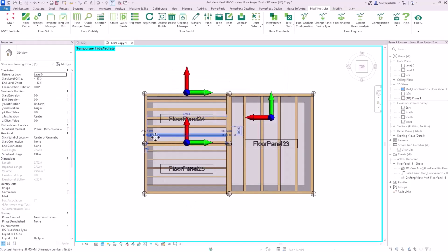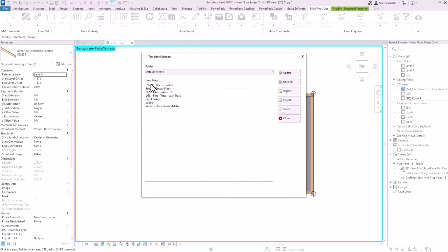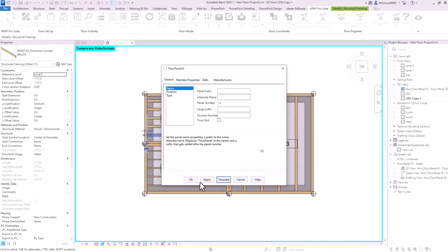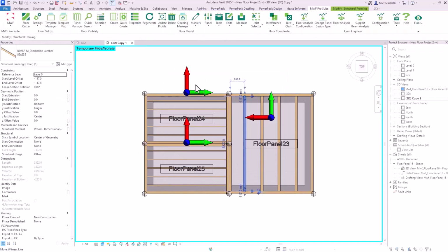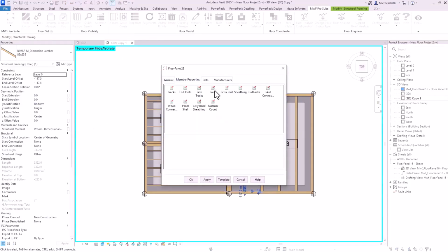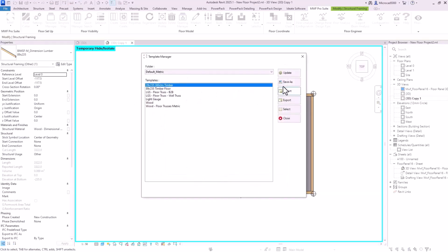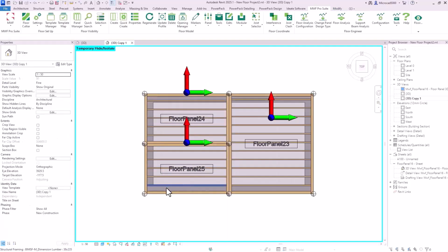So nothing will change there. So do the same on this one. Properties. If I select a template, we want 39300 centers, select, and OK on that. That's better. Again, operator error. And there, properties. So yes, with your template set up, it makes it so much quicker to frame these things up. And as I say, if you set it up with mapping as well, then you just run the mapping, select, and OK on that. Yes, with the mapping grid and all those 3 floors at once.